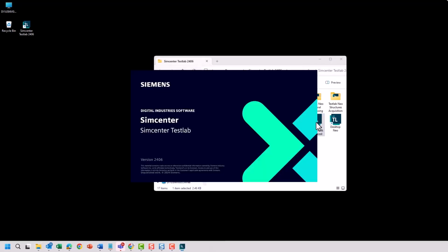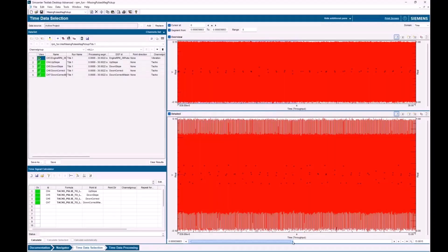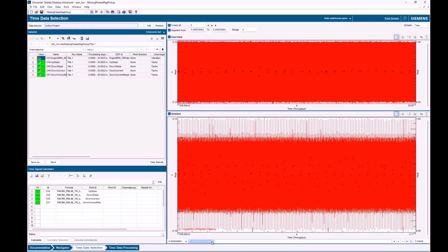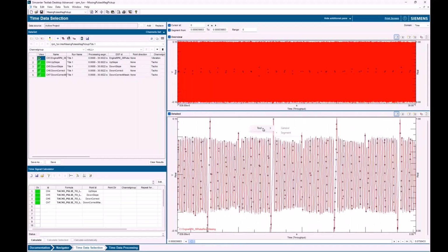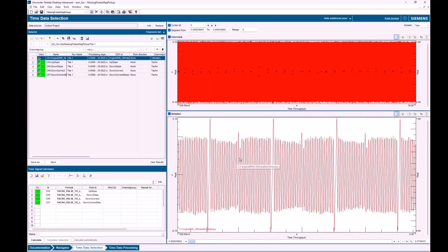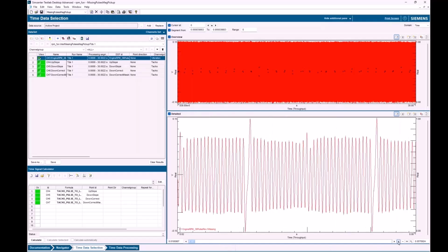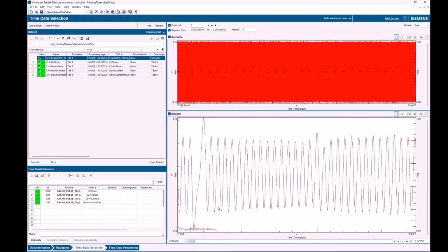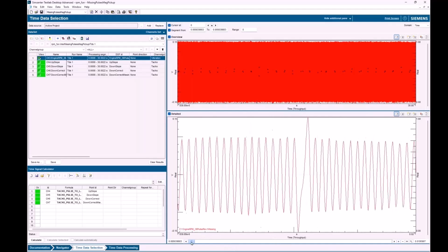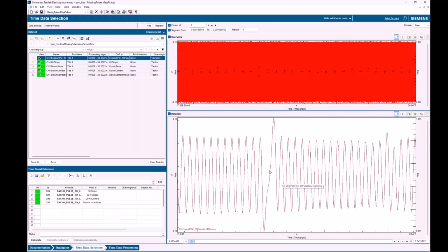Let's look at some other data here. All right, so I got a signal here. This is from a mag pickup, and you can see that we got a bunch of pulses. There's 36 pulses, or at least there should be, but this particular gear that I'm pointing my mag pickup at, Charles, yep, it's missing a tooth. Can you see where it's kind of missing there?